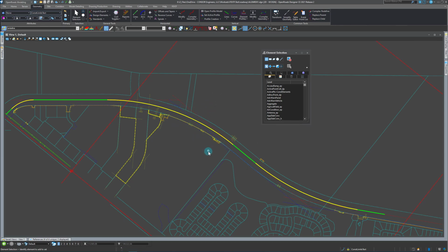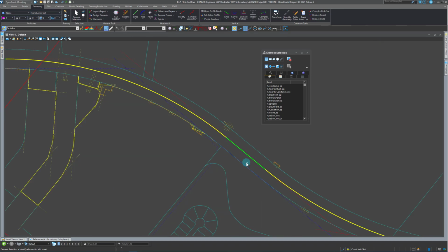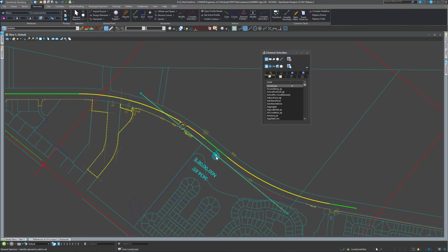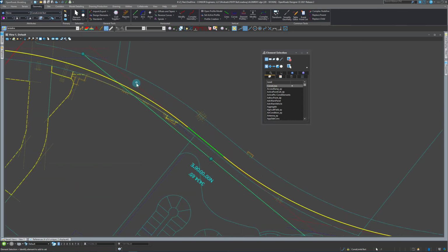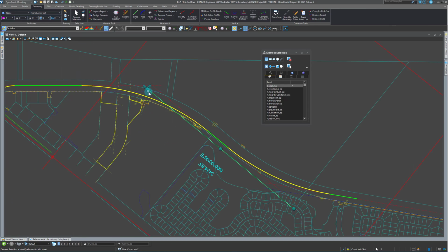Let's say we decided that maybe this isn't the right of way line or something. So I could always move this line over and it shifts. So I'm still 94 feet off of this line, or whatever this is, 102 feet. So this allows me to have some controlling elements to shift this right of way around.